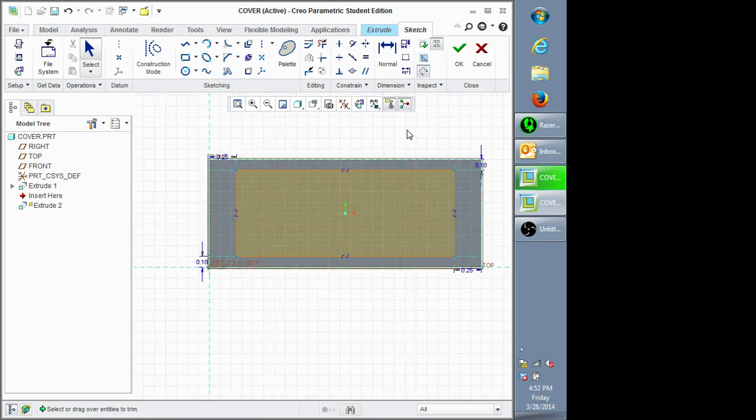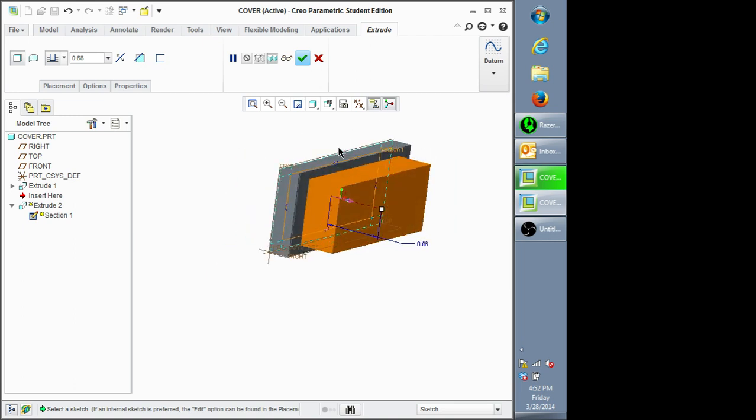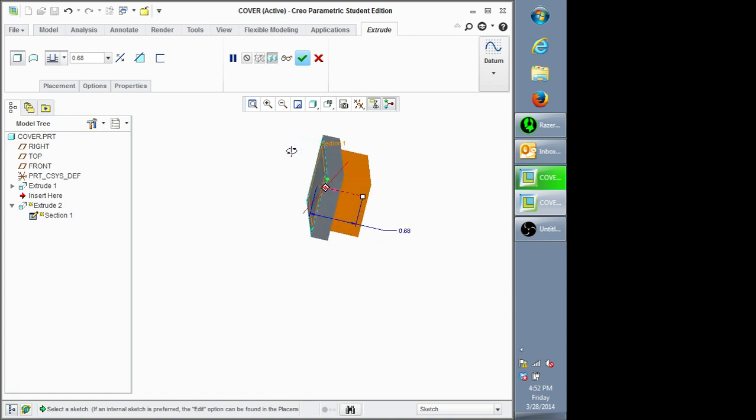If you middle click, you should leave out of that function, and now it's all highlighted, which means it's good to go. So when that's all done, you just click the OK button, and it'll extrude. Notice that we want it to be a cut, but now it's actually extruding a solid. So to fix that, it's actually going in the direction that we want. It's hard to see, but it's starting in this plane right here. So let's put in the thickness first that we want. Let's make it probably about halfway into the metal plate. So let's do 0.125.